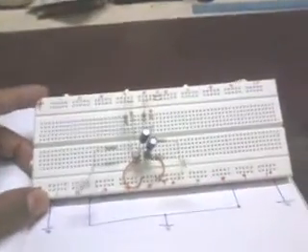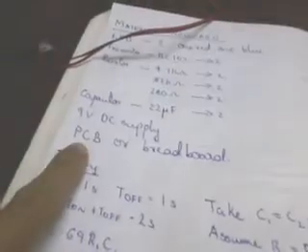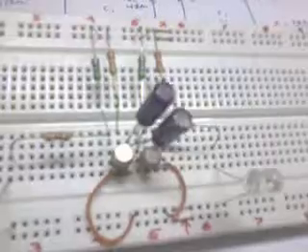So firstly you have to place these transistors Q1 and Q2 very close to each other, and then you can place other parts. You can place the resistors and capacitors exactly as shown in here. I have done a breadboard, so it will be very difficult to place it on small cars or on bikes. So you can also use a PCB. I have mentioned here. If you use a PCB, you will require very small space, and you can make this small circuit.